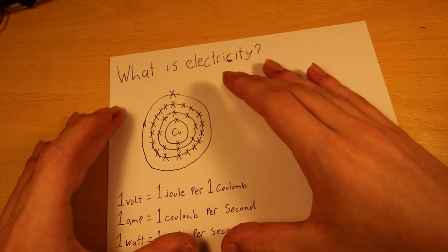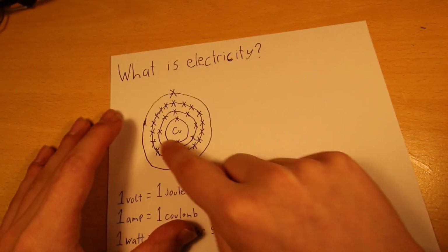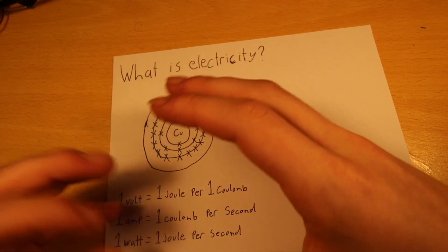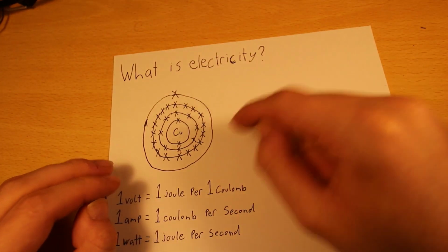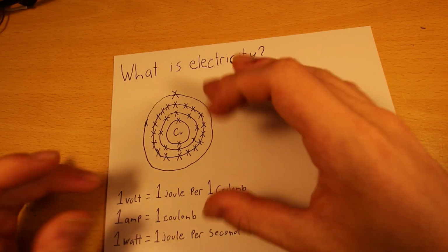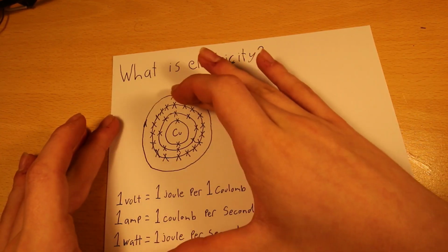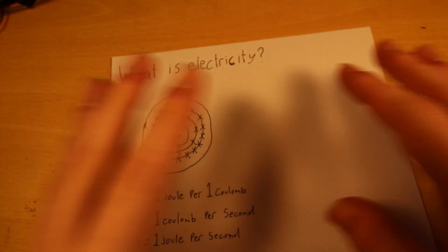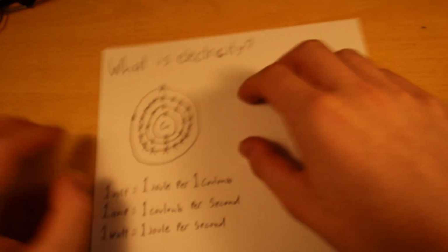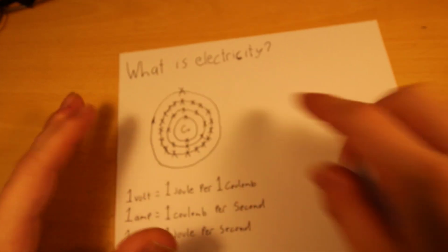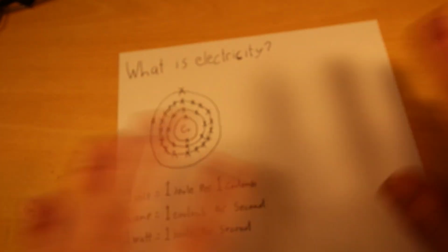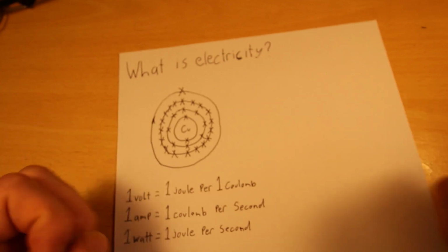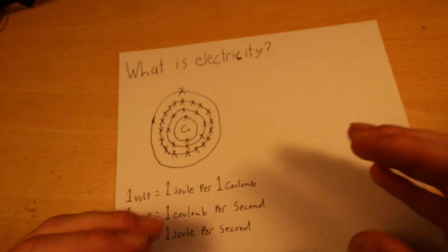Copper, we can see, is a very good conductor because each of these circles is what's called an electron shell around the nucleus of the atom, and each of those crosses is one electron. As you can see, copper has in its outermost shell only one electron, the rest of it is empty, which means it can very easily pass that electron between the atoms. So when you have lots of copper atoms all around each other, these outer electrons can quite easily flow between the atoms, and they move around like an ocean almost between all the atoms. That makes copper very good at conducting electricity because electricity is just the movement of those electrons.